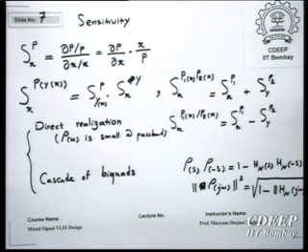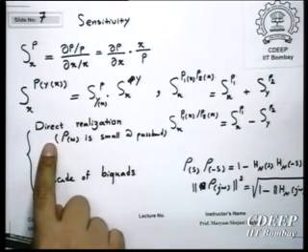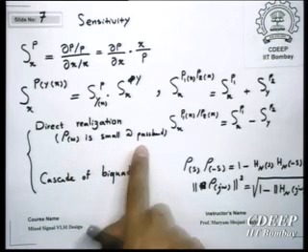Suppose we don't have ripple and this is an ideal filter, therefore magnitude of H will always be 1 in the passband. That means that rho as a function of omega is always 0 in the passband. Therefore we will have a minimum sensitivity. In fact, ideally sensitivity will be 0 if rho is 0. That is a very important characteristic of this direct realization. Therefore, in direct realization, rho(omega) should be kept small in the passband.